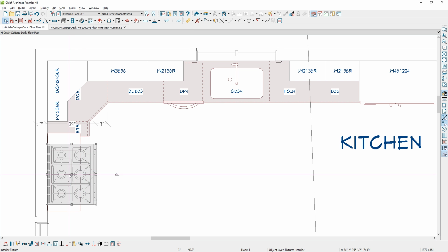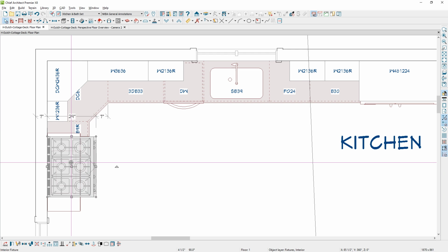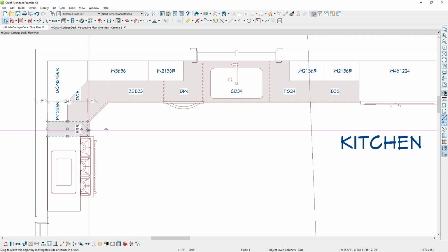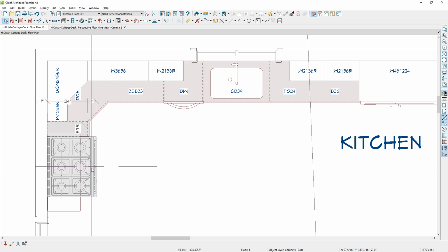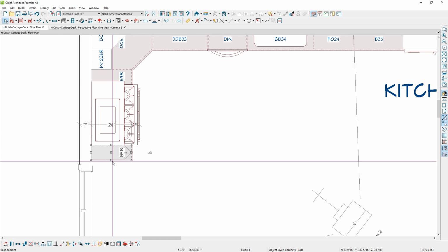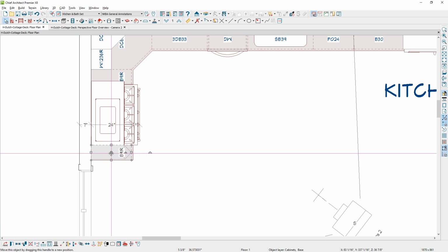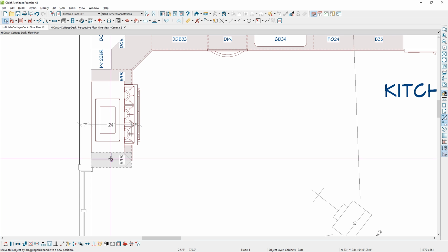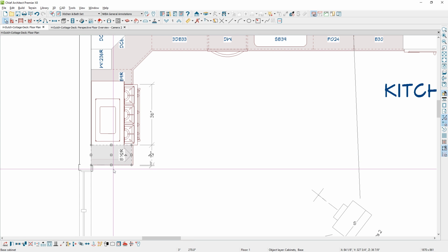Let's go ahead and select that cook range. Bump that to the cabinet, and then just take this cabinet here and create a copy of it and reflect it around that cook range. And then I'll just resize that to be a 12-inch cabinet. By the way, there is a feature now that will bump to the casing. That's new in version X8 and newer.